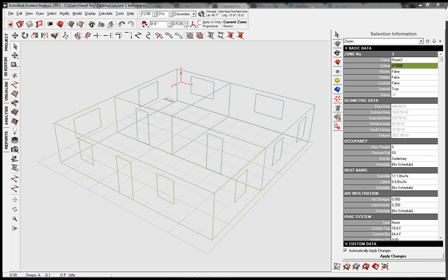The passive gains breakdown informs us about the various heat gains and heat losses that occur through heat transfer mechanisms within a zone. These mechanisms include conduction, sol air, direct solar, ventilation, internal and interzonal gains and losses.